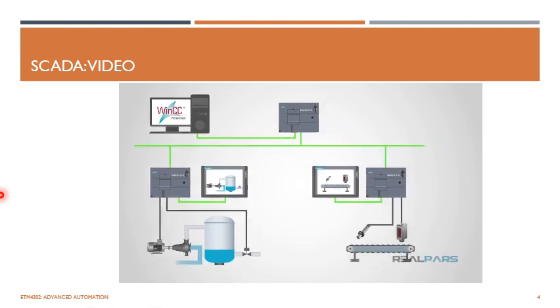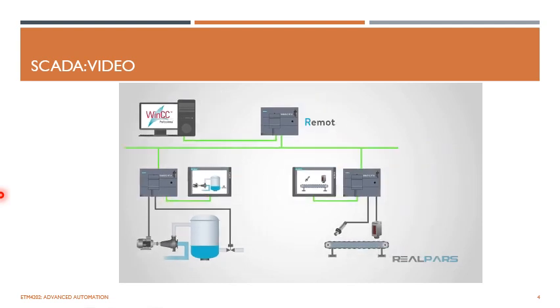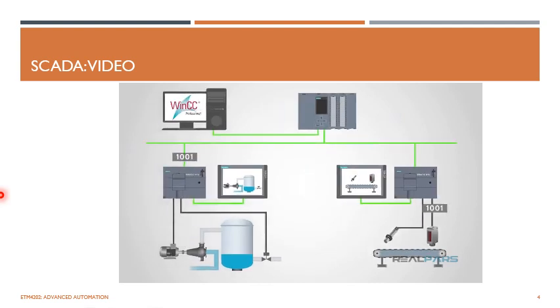The structural design of a standard SCADA system starts with remote terminal units, or RTUs, and/or programmable logic controllers, or PLCs. As you know, RTUs and PLCs are microprocessors that communicate and interact with field devices such as valves, pumps, and HMIs. That communication data is routed from the processors to the SCADA computers, where the software interprets and displays the data, allowing operators to analyze and react to system events.